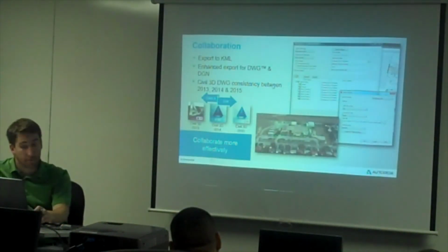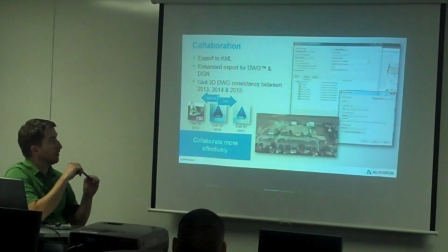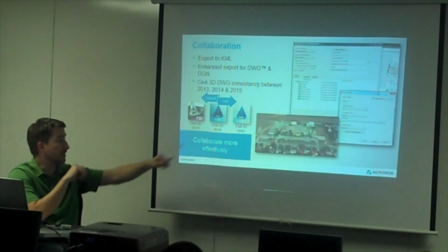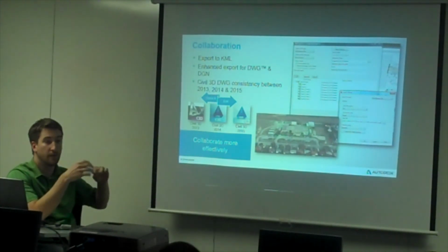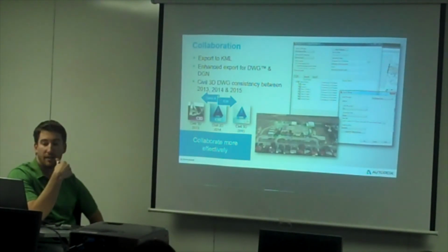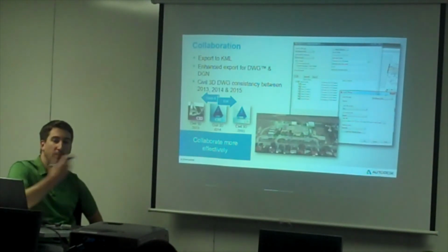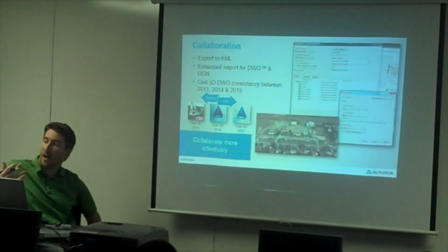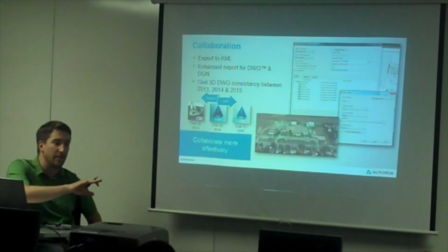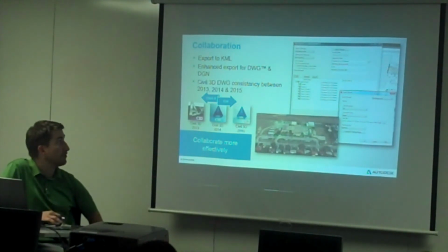And then they've also got some information here about collaboration. They've been doing a really good job with Civil 3D the last couple of releases, since they got to the new drawing format in 2013, of making the data go forwards and backwards: open, edit, save across the project team. Historically, you used AutoCAD Architecture, MEP, Civil 3D, you know that when you pull something forward, it updates those objects into that new format, even if it's the same DWG format, but you just don't have a lot of success going backwards without losing something. And so you're able to do that now.